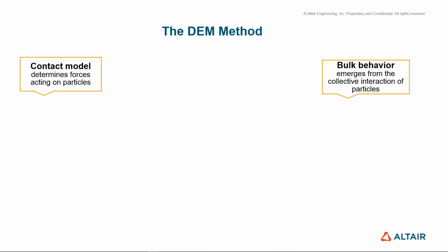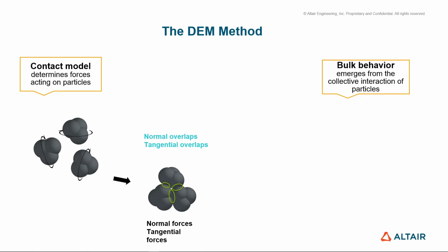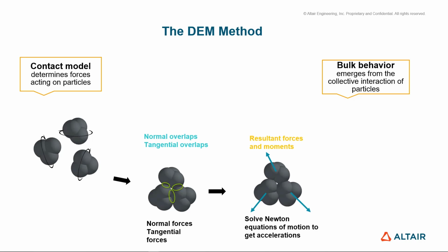So DEM works when particles are in contact, by applying a contact model that describes the physics of how particles will behave when they are in contact with each other or equipment. Then EDEM is capable of calculating forces acting on those particles. And after updating positions, the software looks for new contacts with other particles or geometries. We get the updates, and finally the whole process starts again. So this slide summarizes the basic principle of particle behavior when using EDEM.